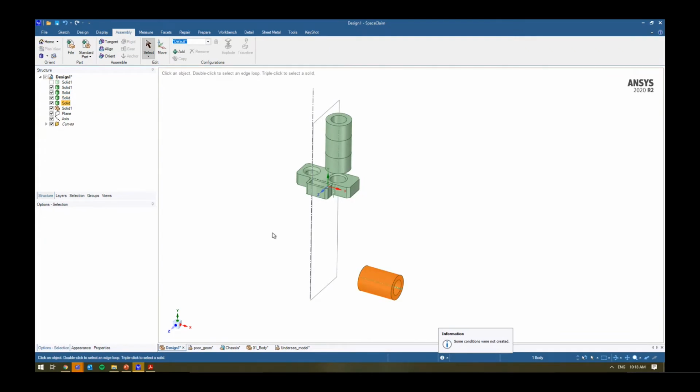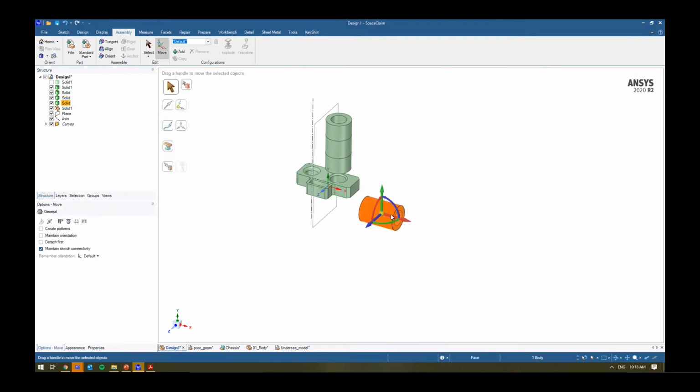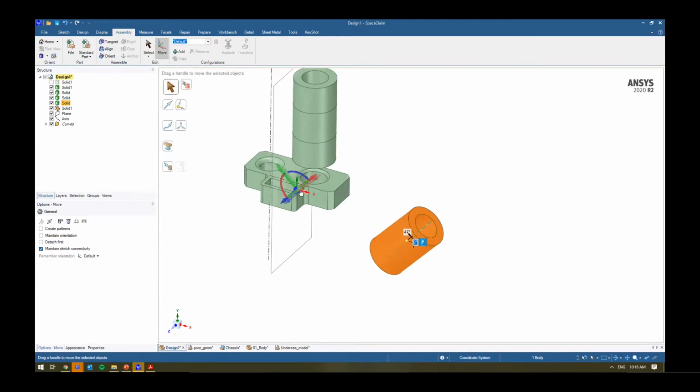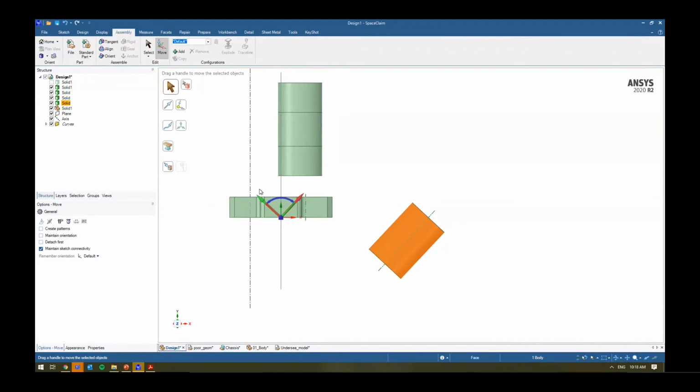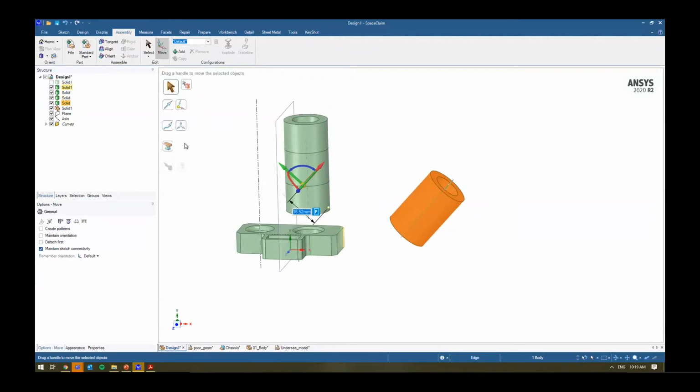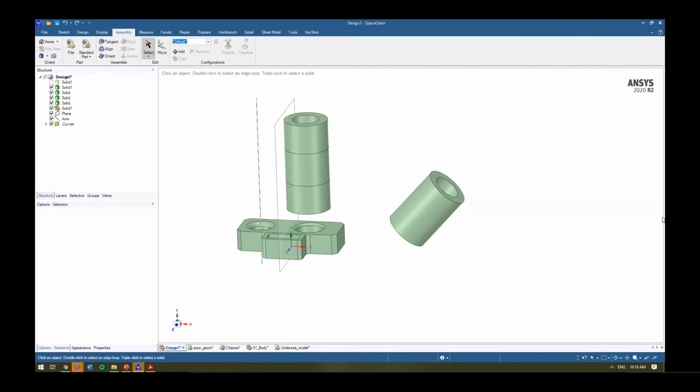And then you can go in and you can use your move tools afterwards to move things along in a specific direction, change it by an angle. Again, I can move this, so instead of having the pivot point on the object, I can move it, say, from a location, right, from the axes, and move it around that way. I can even change the anchor point as well, right? So if I say change it up to there, now I can move XYZ kind of relative to that component there, right? There you go. Make some changes. So hopefully you can see how, if you've got something that's brought in, you can use some of your assemble tools to play around with it, right?